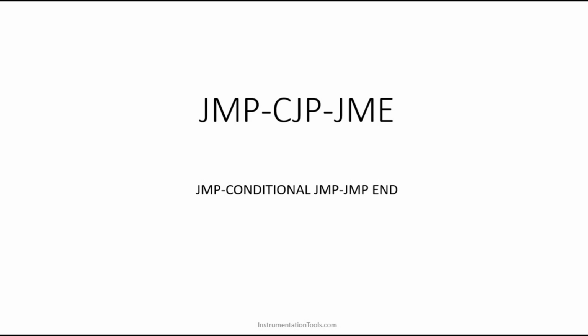In this session, we are going to see about the jump instruction in Omron PLC. So, what is the purpose of the jump instruction? It is going to skip some rungs in the ladder logic. For example, you are writing a project of 100 rungs, and in some situation, you want to skip some particular number of rungs.